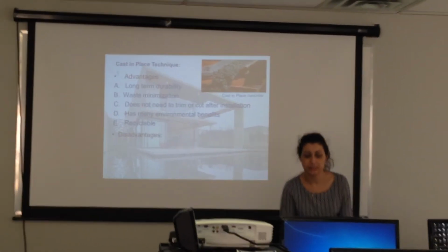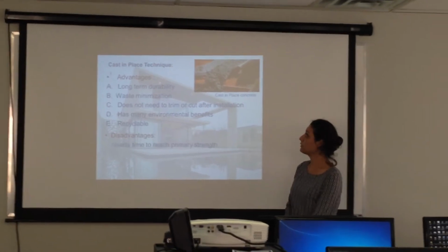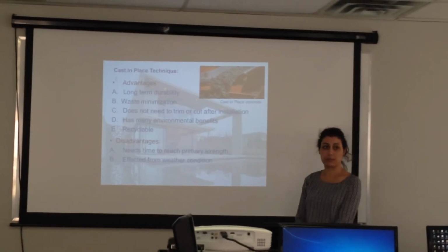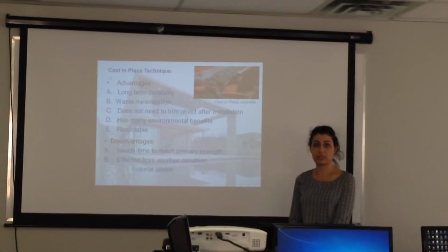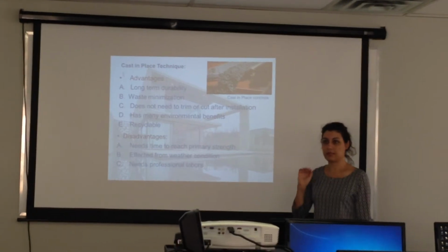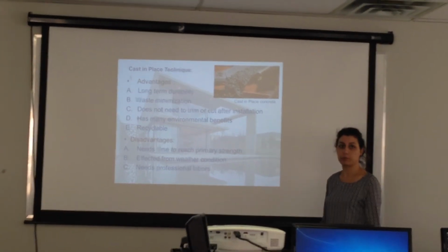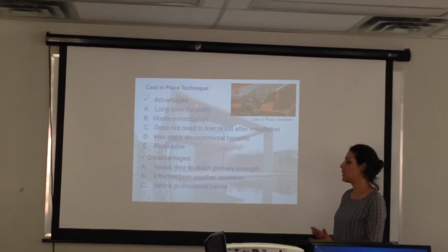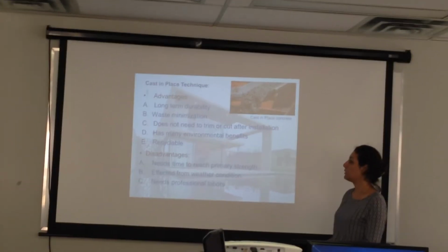What about the disadvantages of this technique? We can see that we need time, as I mentioned, at least 3 days for concrete to meet the strength point. So we need time to reach the strength that we need for that purpose.